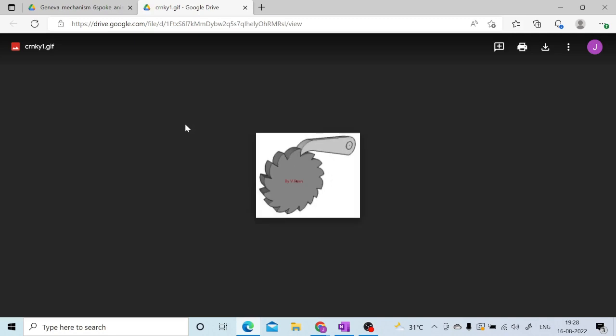It is kind of self-locking, or we can say this is a self-locking mechanism, so it cannot come back by itself. That particular link which is rotating in a particular direction, the link which has halted at a particular place, cannot come back. So this is how it is a self-stopping mechanism. So this is the ratchet mechanism. This kind of mechanism is there in watches and all. I guess it is utilized over there.